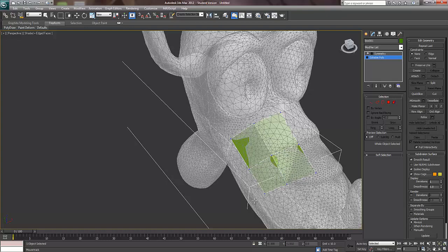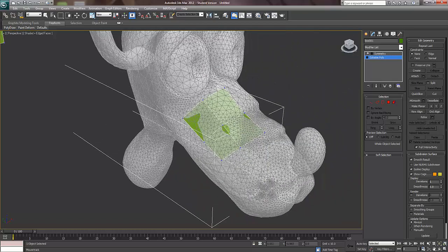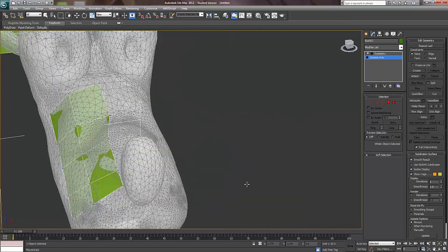Hold Alt and left click one of the verts, it will delete that edge. So if you make a mistake you can just delete it, or Control Z. We're going to create the faces here, keep going around. Essentially the retopologizing tool inside Max. It's very fast.